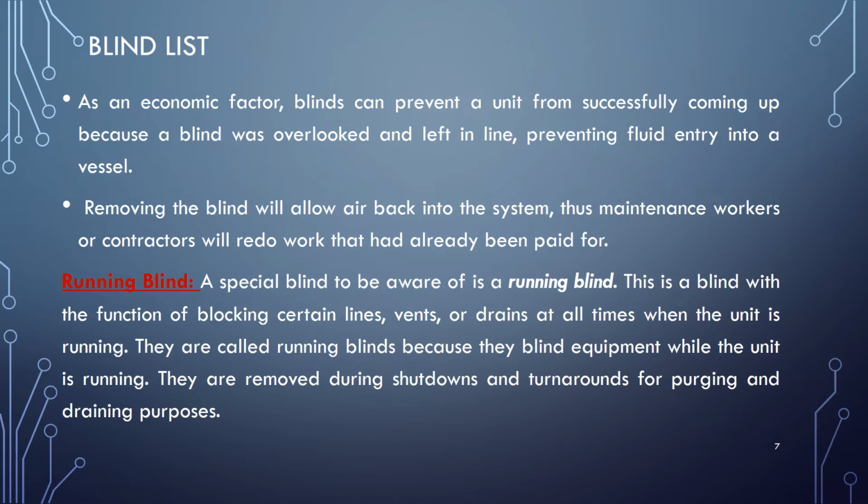If you are taking any equipment, you all are aware, while I am going to run the unit, just assume it's a reactor, I have to close that vent as well as the drain. You just assume they are collecting at this place. I have to close the drain as well as the vent. These two parts of an equipment we must close, if it is a reactor or column or separator, anything. You got the point.